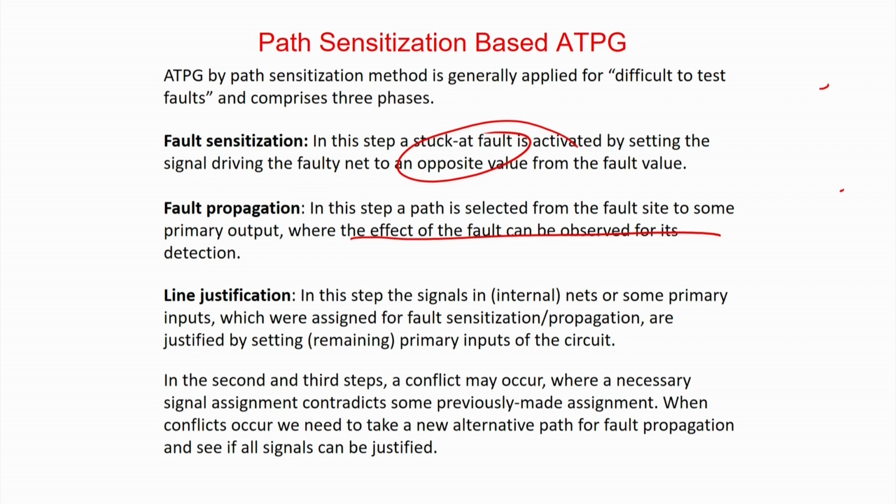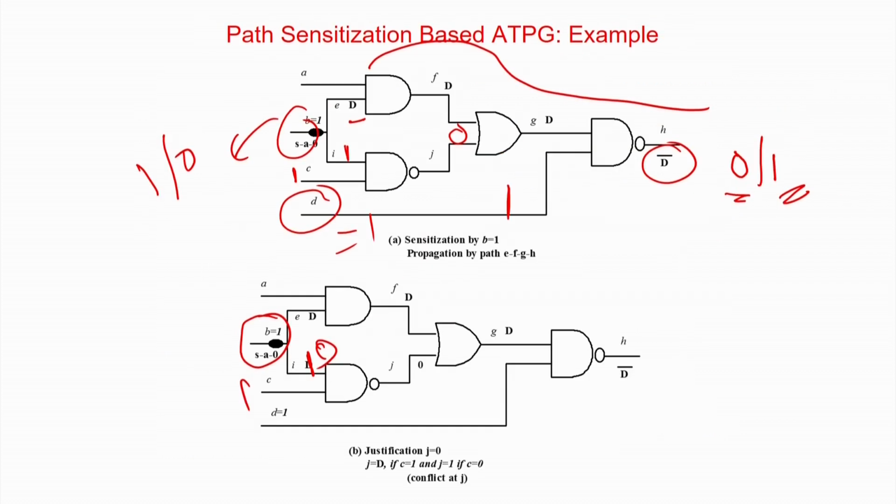So basically this is the heart of all tests, that is you are given some faults, you have to find out what test pattern to apply. And as I told you, in traditional circuits our job was to get 100% fault coverage. That means some of the faults will be covered in a random manner and whatever will be remaining will be handled by this ATPG approach, that you have to target each individual fault and find out in this manner, so that we get a very high amount of coverage. But when you will be moving to SOC NOC level paradigm, even this will be blowing up, because the number of difficult faults will be also higher.